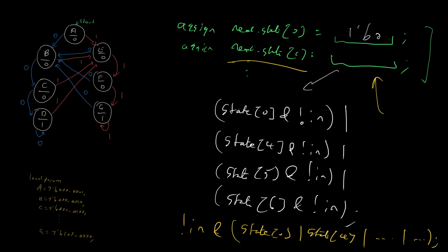And why is that useful? Well, for two reasons. Firstly, the total number of logic elements used. So yes, with one-hot encoding we need to use more flip-flops, but often that's more than balanced by the fact that we use a lot fewer lookup tables because the combinational logic for the next state and output logic is so simple. The other benefit, which we will appreciate even more a bit later in the course, is that if the next state logic is very simple, then it can be computed quickly.